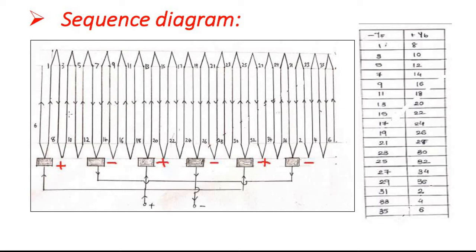Now it's time for the remaining conductors. The remaining conductors are given direction alternately. So this is upward, so downward, upward. Then both are downward, then upward, downward. Both are upward, so downward, upward. Like this, mark all the directions for all the conductors used in the diagram.